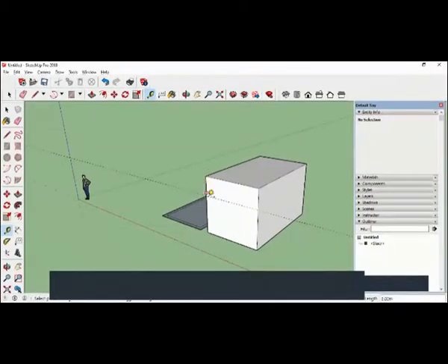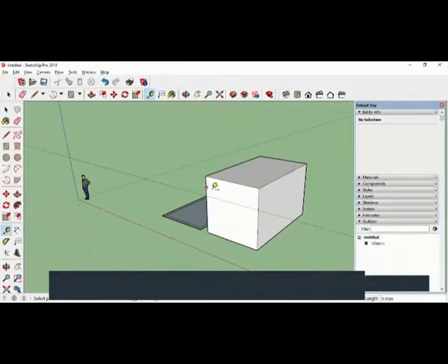Now suppose I want to draw a parallel to this vertical line. So I will select that line, move. Sometimes you don't see it because you have to be very careful. Click. And you can see that now it is showing. When you are dragging it, you can see a red dotted line, which shows you that you are drawing this parallel to red. Okay, so 1 meter. And here also I want 1.